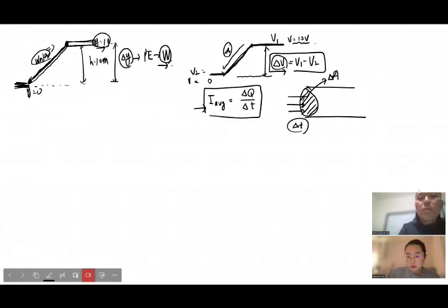that is normally called the current. So current is basically defined by a finite amount of charge traveling across the cross section in unit time. The more time you monitor in a given area of wire, the more charge you will see passing through this cross-sectional area. So basically the current is the ratio of the charge moving across the cross section of the wire in a given time. Here delta Q would be Q2 minus Q1 over T2 minus T1. It's just like the velocity concept, obviously a different physical quantity, but the way of defining this average current is the same as the velocity from displacement in a given time.